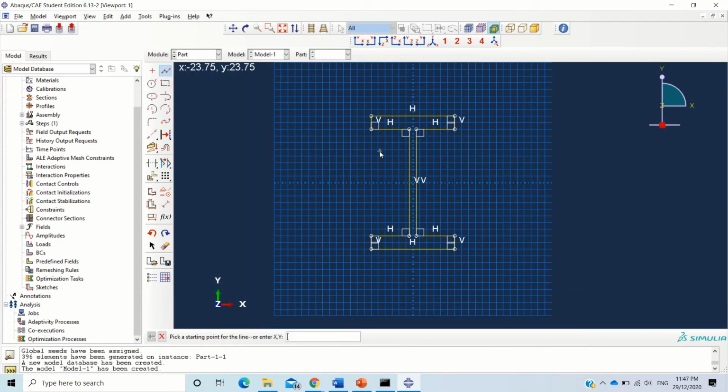So it's done. This drawing has a closed profile. Next we can double check our dimensions. This one should be 60, okay. This one should be 80, also okay. This one also 60, okay. The thickness of the flange is 10, okay. The top flange also 10, okay. The thickness of the web should be 5, looks okay.